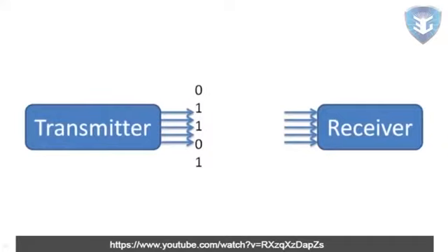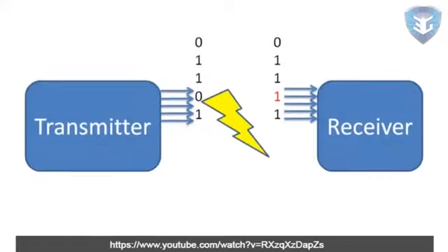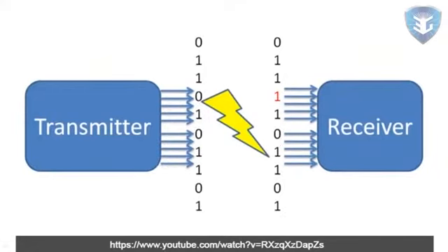Now, how do we intelligently increase the distance between two code words so that we can detect errors? Naively, we could increase the distance by sending a message multiple times. The receiving component would detect the error by simply comparing the two sets of bits. However, this method is ineffective, and it requires a lot more hardware and would become expensive very quickly.